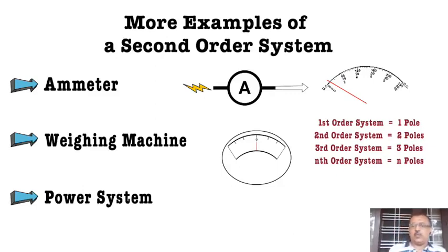And what is the output? The output is the frequency. We want the frequency to be 50 hertz. This problem is called load frequency control. When the frequency comes down, the KSEB engineers will open up the valve. Opening up the valve is equivalent to a step input. I'm simplifying it extremely, but the physics is the same.